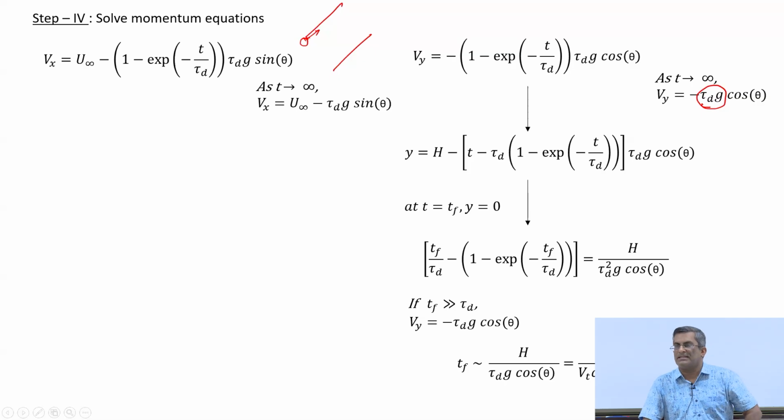So again, in this case, if we assume theta is equal to 0, or a horizontal channel, then what do we get? The height divided by the terminal velocity, which is again as expected. Distance divided by the velocity. Why terminal velocity? Because in this case, the particle is reaching the surrounding fluid velocity quickly under this assumption. Okay. So this is again a check to see if we are getting the correct answer.